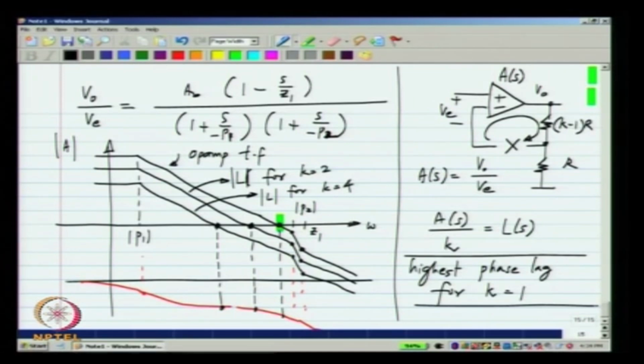Okay. Now, this is relevant because normally when you design an op amp without any further information, you simply have to assume some value of k. Obviously, the value of k that you have to assume is the worst case, which is in this case 1. That is, you assume that whoever is going to use your op amp can use it with various values of k, and you design it for the worst case, and the worst case happens to be 1. So, if k is 1, the loop gain is nothing but the op amp's gain itself. So, it is easy, in a way you can design the whole thing without worrying about which feedback loop there is. You evaluate the gain of the op amp and assume that that itself is the loop gain and adjust it for stability. Okay. Now, this is not a general procedure.